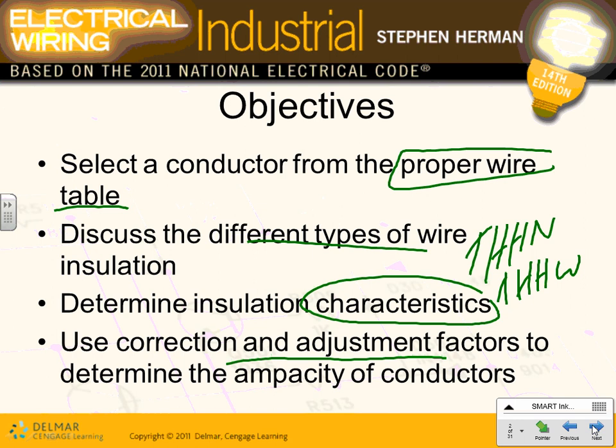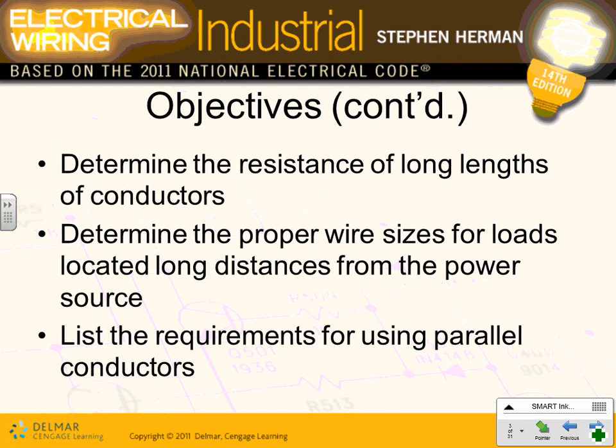If you're feeding with number 12 or number 10, it doesn't make a lot of sense, guys, to start grouping. If you have number 10, maybe number 8 at the border, but higher than that, number 6, dedicated branch circuit. You have a number 6 for a 3-phase load, dedicated branch circuit. Okay, these are opinions though. Code-wise, you can group anything you want. Definitely, you don't want to group any feeder or branch circuit that's 100 amps or more with anything else. It's just not a good idea.